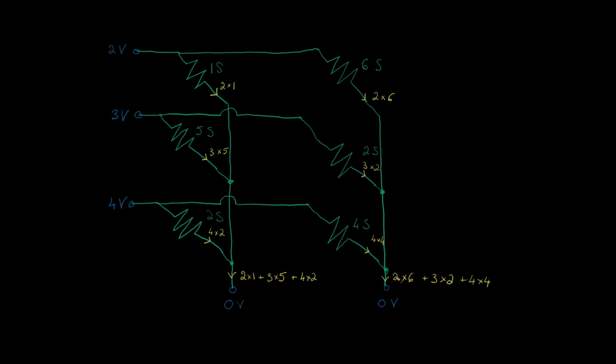Now, for the voltages, it might not be that difficult to change them. There are devices that can apply arbitrary voltages here on the left. But for the resistors, it's a lot more complicated, because we'd have to pick different resistors each time we want to compute a different vector matrix product. We'd have to essentially fabricate a new version of this circuit each time.